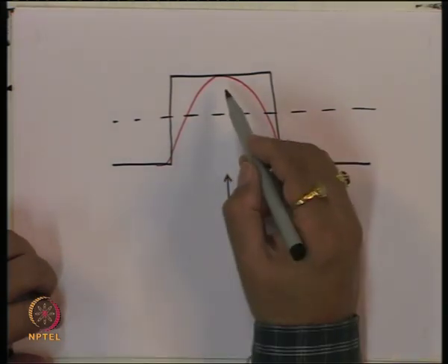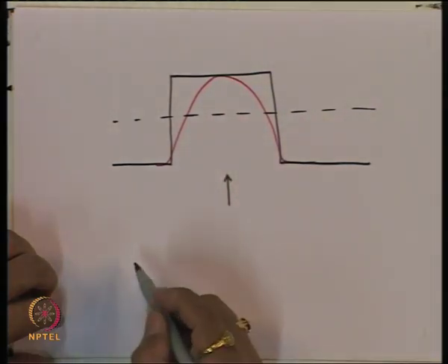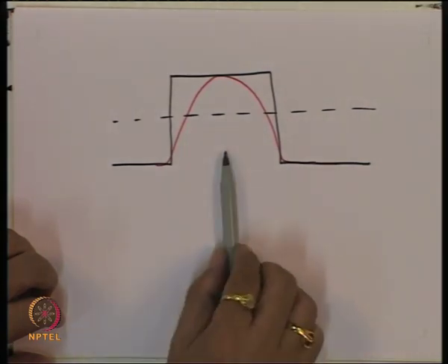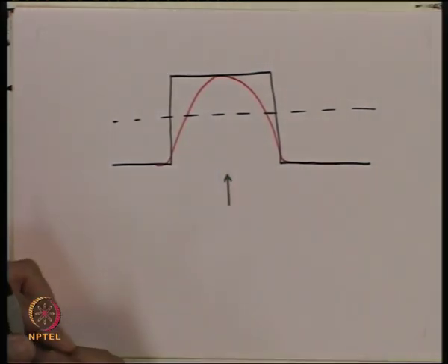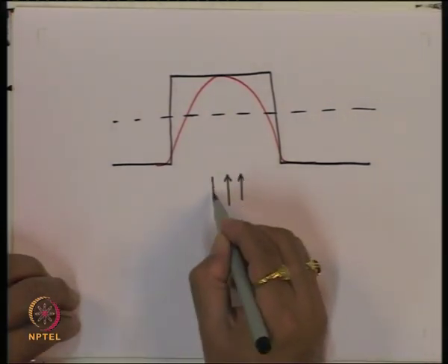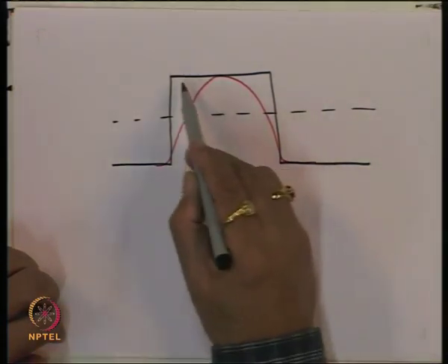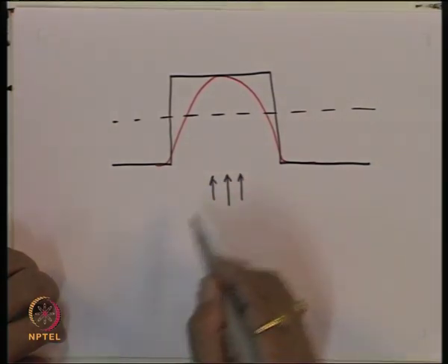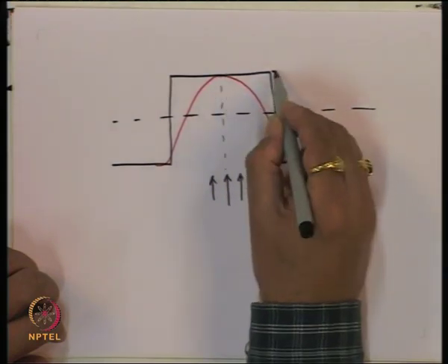So, now if we are having now a timing jitter, that means on this function, the sampling point essentially is having a random fluctuation. That means sometime we sample here, sometime we may sample here, sometime we may sample here, and so on. Now, since this function is not constant over this time when I am sampling, when I sample here, we get an amplitude which is this.